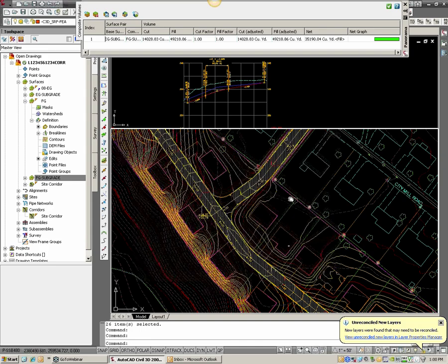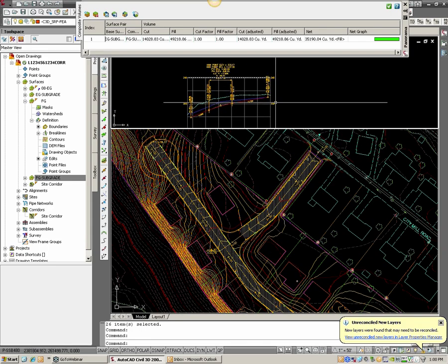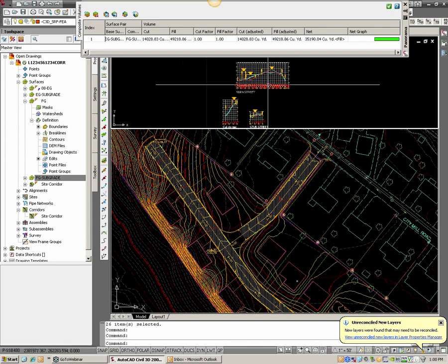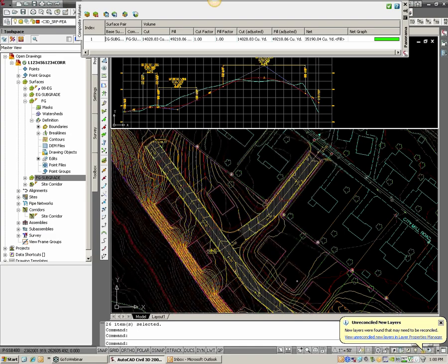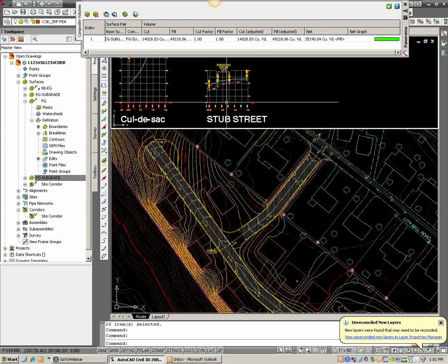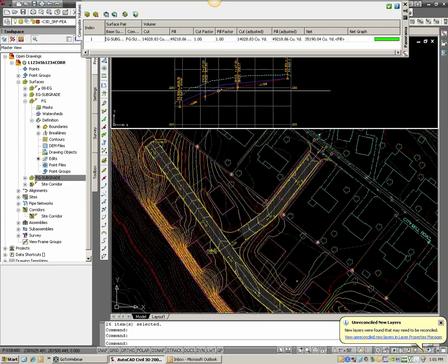To leave off here, I told you I'd show one more little trick. When we move this road up and down, right here on this main drag, right about where the crest of the hill is, a stub road comes in. So now that I move this up, I really need to adjust my stub road grade. Well, how do I even know where to tie it in?